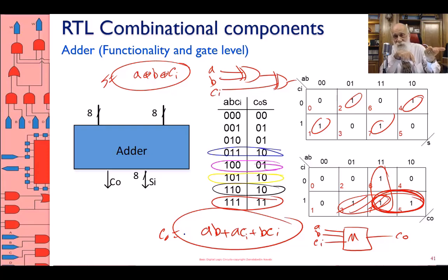Go back and look at the multiplexers and you see that using two 4-to-1 multiplexers, I'm able to build the sum and the carry. So your choice of how you want to build this is up to you. You can build actually complex gates. You can use transistors, but all there is to it is one slice does it all.